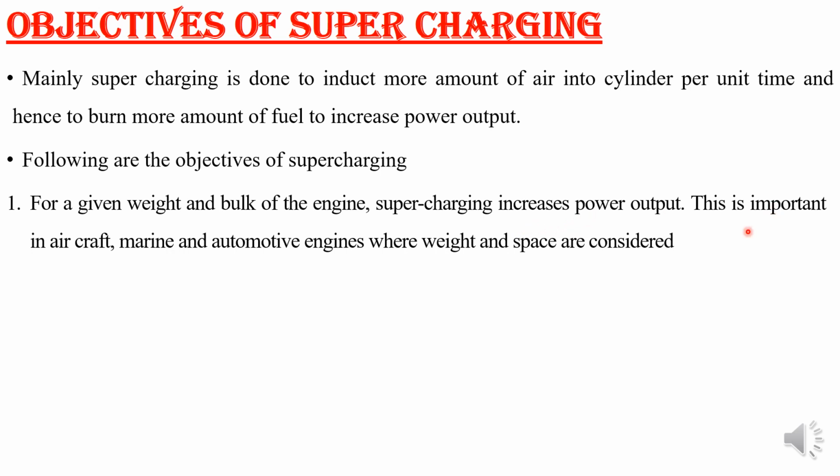This is important in aircraft, marine or automotive engines where weight and space are considered, very importantly in aircraft engines where you work at high altitude and want to reduce weight but need more power output, so supercharging has to be done.